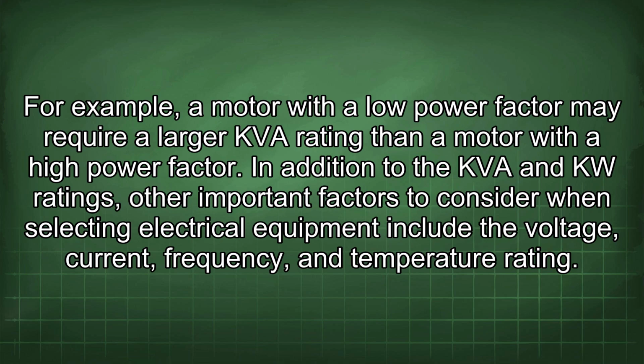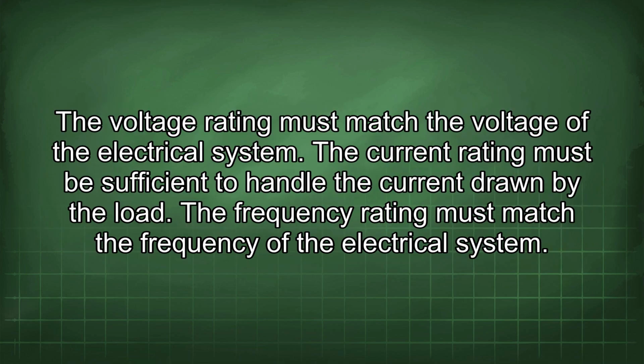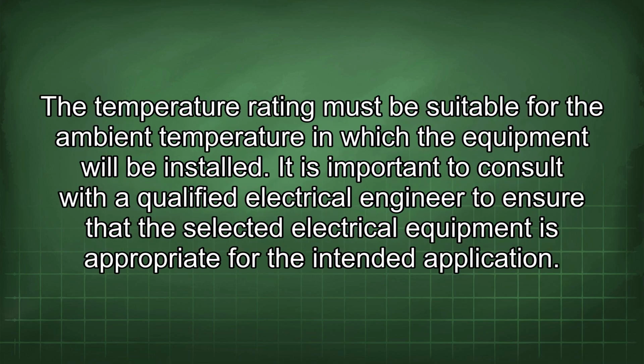high power factor. In addition to the KVA and KW ratings, other important factors to consider when selecting electrical equipment include the voltage, current, frequency, and temperature rating. The voltage rating must match the voltage of the electrical system. The current rating must be sufficient to handle the current drawn by the load. The frequency rating must match the frequency of the electrical system. The temperature rating must be suitable for the ambient temperature in which the equipment will be installed.